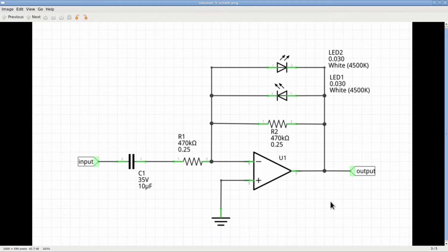This will happen, of course, at the expense of the shape of the input signal, which will be flattened out when we exceed those plus-minus 2.5 volts at the input. And that is how this circuit will prevent the voltage on the auxiliary inputs from growing over the 5 volts peak-to-peak value. Let's now move to the lab, and let's see how this circuit practically works.